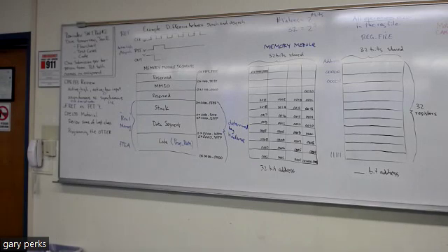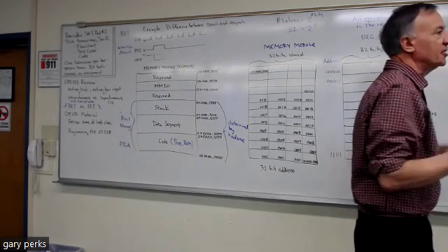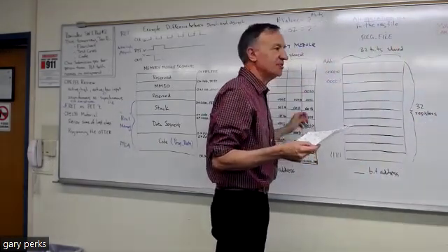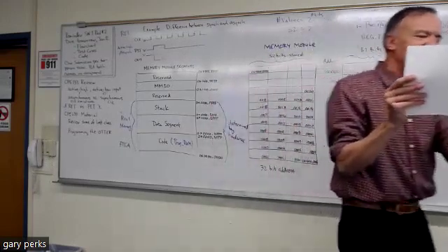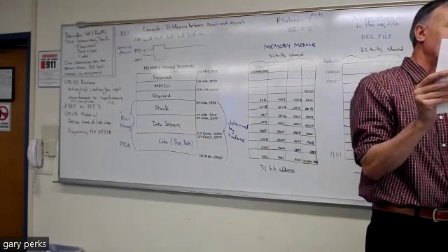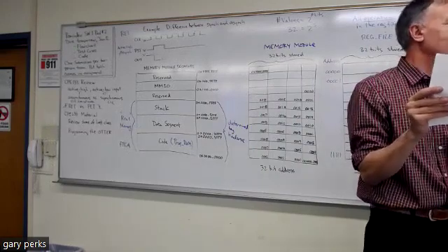The next thing we talk about is this register. You'll see that its purpose is to give the memory module the address of the first instruction of the program. And like we talked about, instructions are a word each, so all instructions are separated. That's why there's this +4 here: every time the program counter gets updated, it increments by 4.